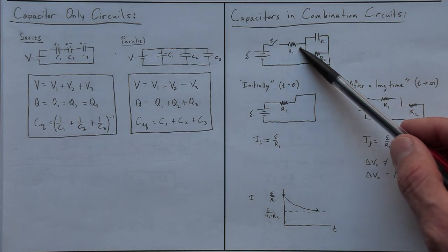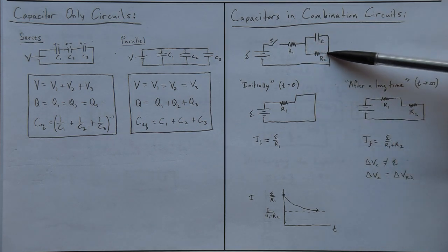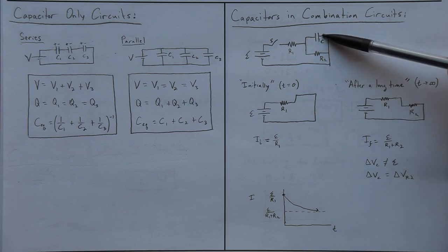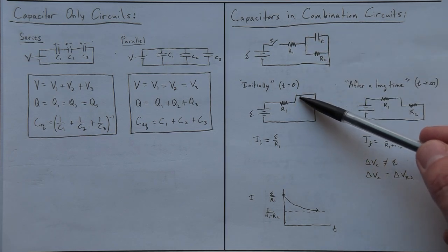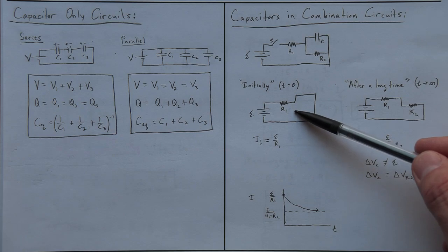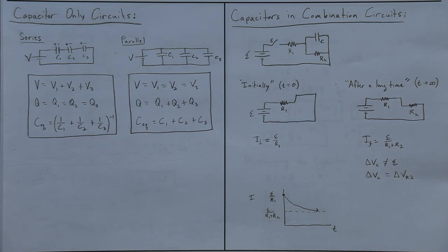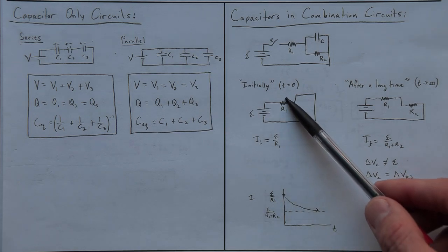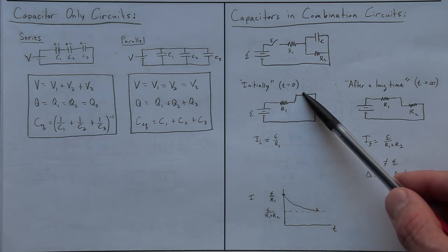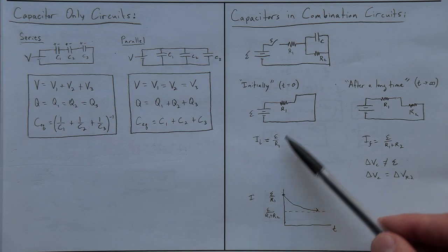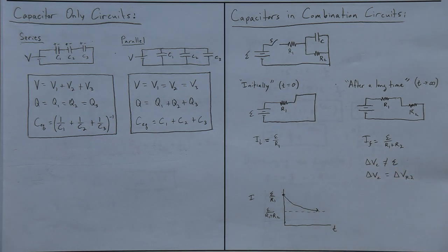So the current, when it passes through resistor 1, will bypass resistor 2, and in that initial moment, all the current will go through the capacitor as a wire. So R2 is completely bypassed. So to the battery, the current is inhibited by only that resistor because it can freely pass through the capacitor. That's only at time equals 0, EMF over R1. That's how the circuit behaves.